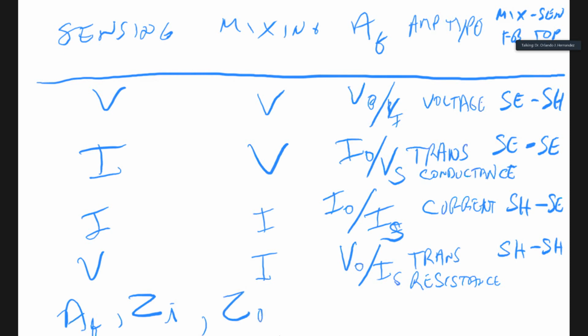how your circuit is going to load whatever is driving it. So that's the input impedance. And you want to know also how well your circuit can drive something else that comes after it. That's your output impedance that relates to that. So these are going to become the main characteristics of amplifier-based circuits that we're going to be looking at.